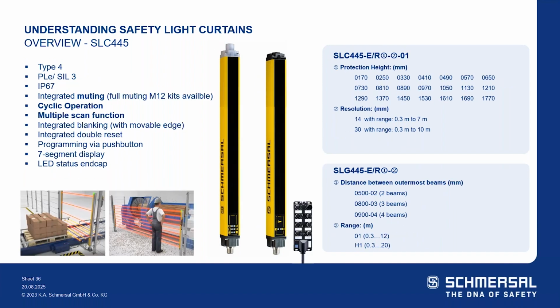Then we move up to the all-arounder. This is our SLC 445 series. So now incorporating all of the features we just mentioned on the previous slide for your 440 series, including now integrating the special muting functions, all of the muting functions we just discussed, with full muting kits available, integrated into the SLC or SLG, light curtain or light grid 445 series, including the special cyclic operation, that multi-scan, as well as the previous blanking and double reset and your onboard EDM, your 7-segment display, the LED end cap, status end cap, IP67.